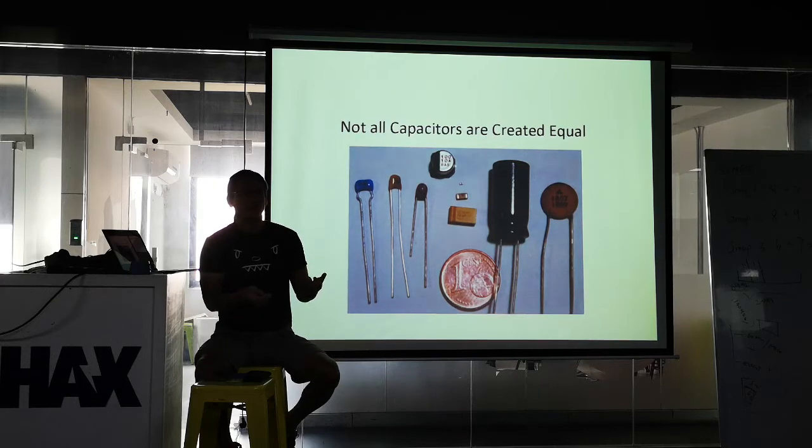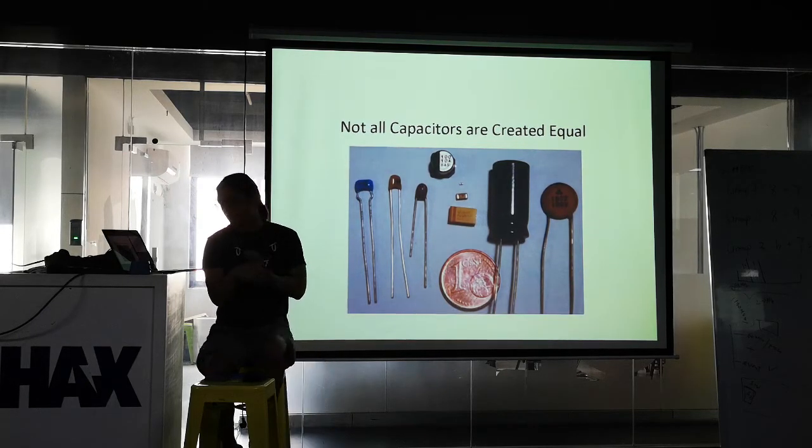So this is one of those tricky things about speccing out capacitors that a lot of people don't necessarily consider. They go, well, why do I care about what dielectric? 10 microfarad, 100 microfarad, use whatever I want, right? The dielectric actually has a huge impact on reliability, has a huge impact on the tolerance and the voltage levels, these types of things.